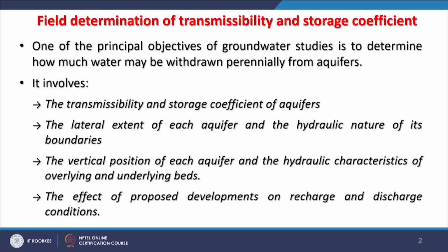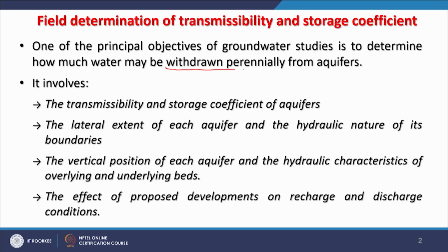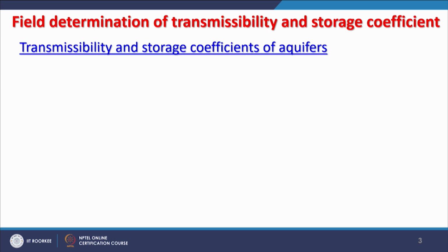And finally, the effect of proposed developments on recharge and discharge conditions, because we have said that we would like to withdraw water perennially, but what are the possibilities of water recharge, or from where does the water get discharged and come into our aquifer? So, all this information is required and can be obtained through field determinations of this kind.